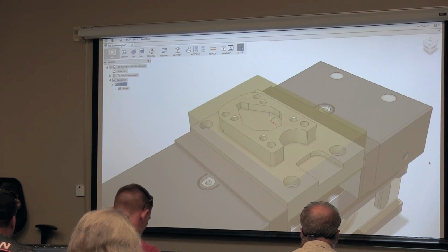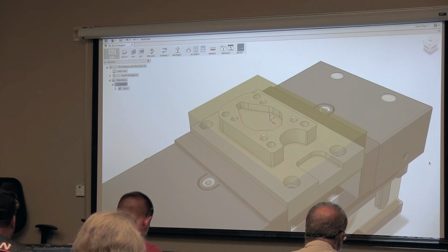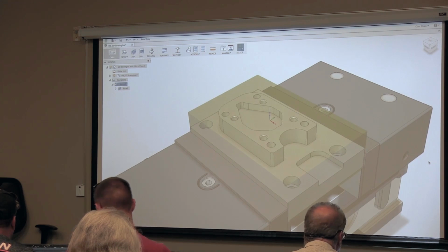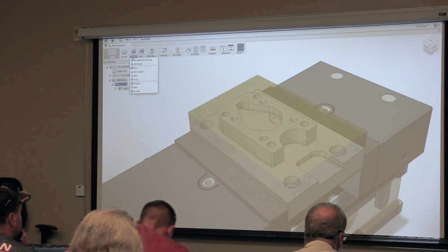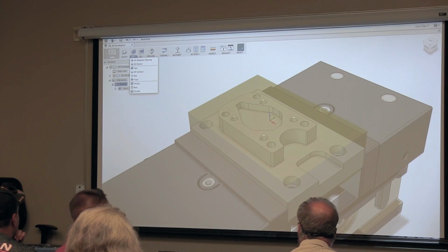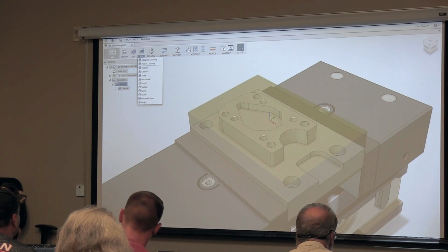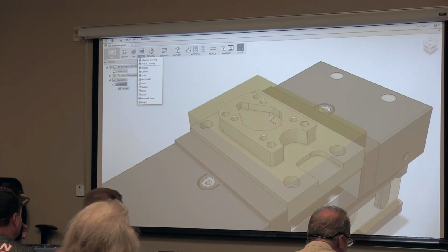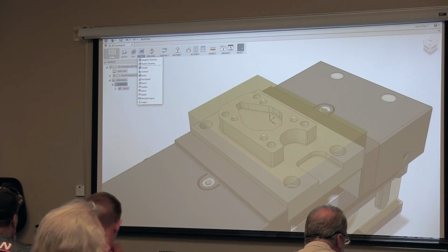But we know we need to rough out, it'd be nice to rough out the top pocket, the outside, as well as that other front pocket that we have there, all in one shot. Adaptive clearing. Yep. Now there's 2 ways of adaptive clearing. You have, if I drop that under 2D, which is 2D adaptive, and then you have 3D adaptive, okay?